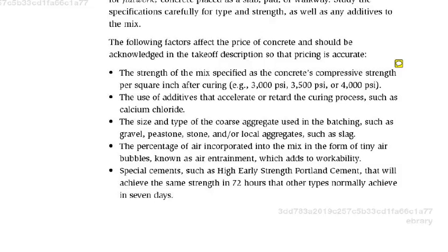Where would you find different stone size? If you're placing concrete for a sidewalk, you can use a larger aggregate. Again, the specifications will tell you how much. But if you have reinforcing cages inside of a column form that you're going to be placing concrete in, your aggregate size will probably be less, because the largest size aggregate you can use has to be able to fit between the reinforcing cage bars. Right? In that case, you're going to have some different concrete.